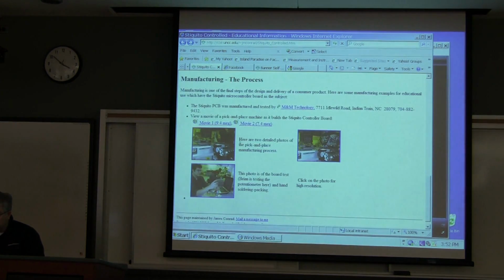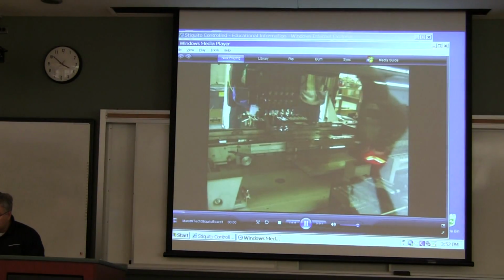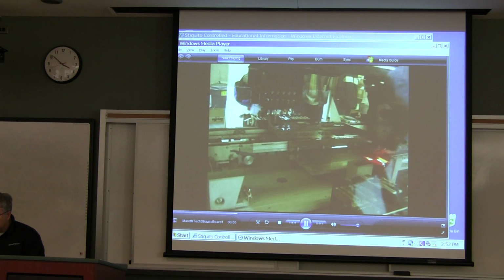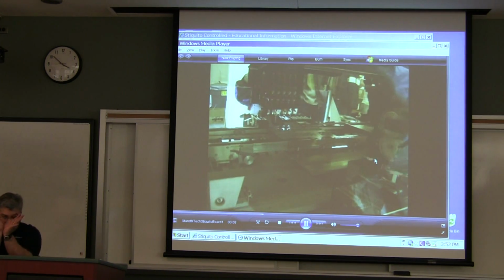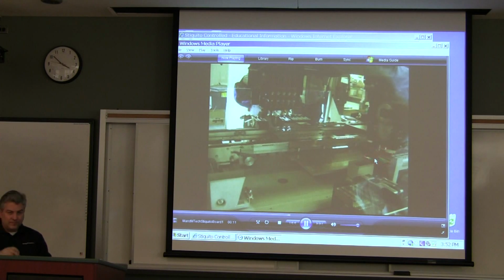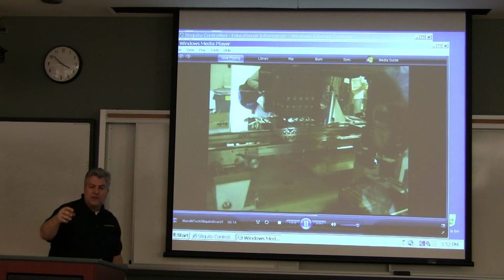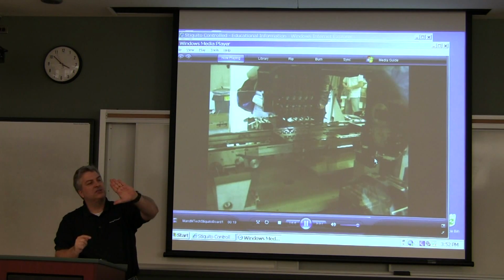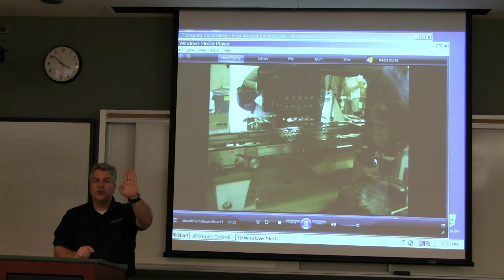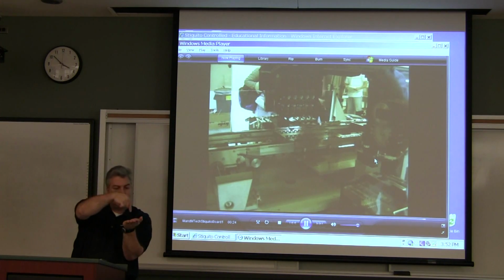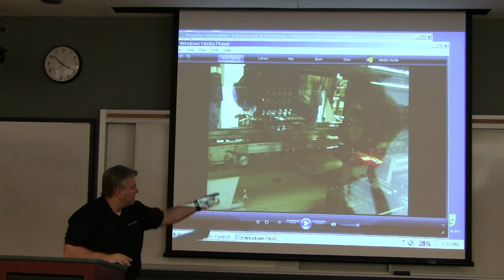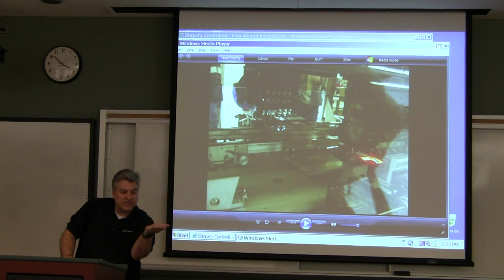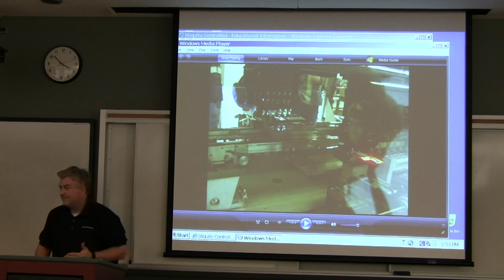So if we look really carefully at how it's going to be manufactured, here it is, picking and placing on this unit here. The camera actually looks at the part that was picked up. If you can imagine, if you're trying to pick something up from a surface, you don't know if it's going to be oriented like this or like this. The only way to know exactly how it's oriented is to take a picture of it as it's being lifted up. That's what it did at the end with the camera, because you have to place it exactly where it needs to be on the board.